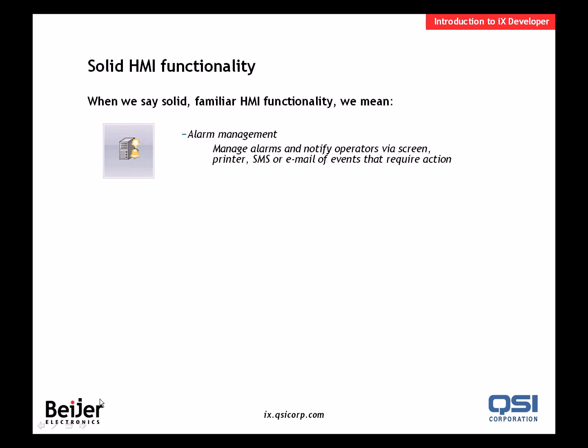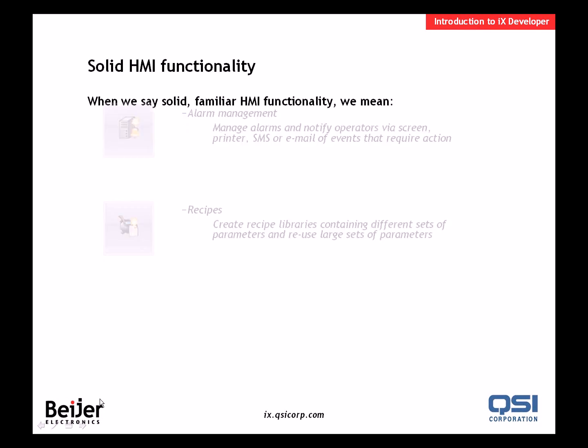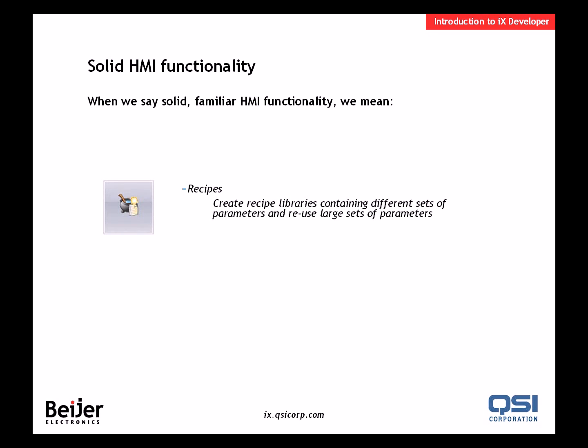We have recipes. Recipes is also very crucial for an HMI application, meaning that in iX Developer, you can create what data items you want to be included in the recipes, and you can even create the recipe data offline when you develop the application. Then in runtime you can load and save or delete the recipes as you want.